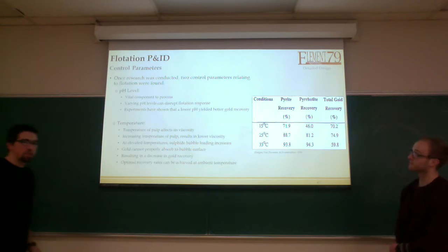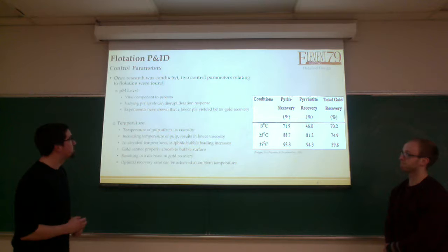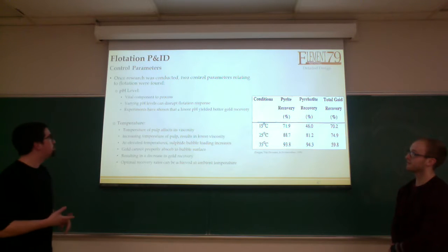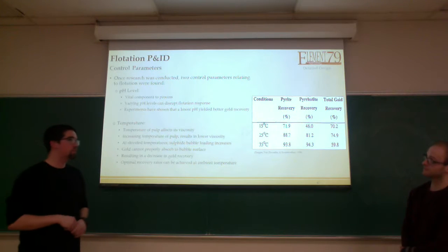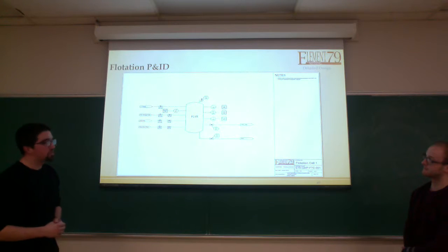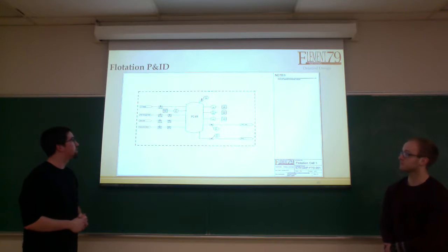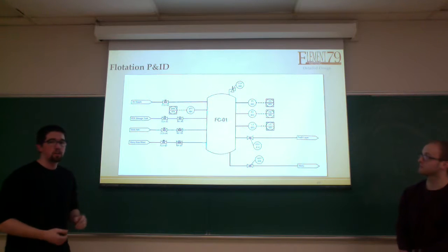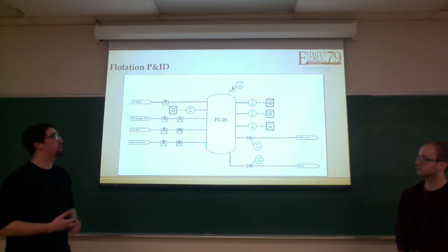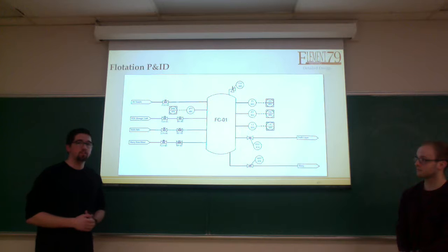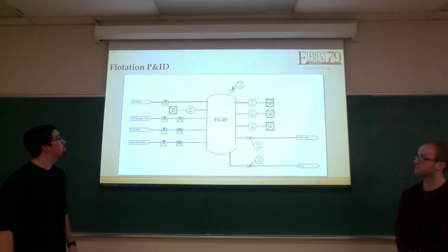So now I'm going to get into some control parameters for the flotation. Two main ones were the pH and the temperature. So that we developed the P&ID just with a few different instruments such as flow control valves, level and temperature and pressure indicators, as well as a PSV for pressure safety.